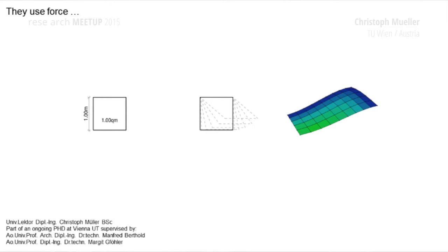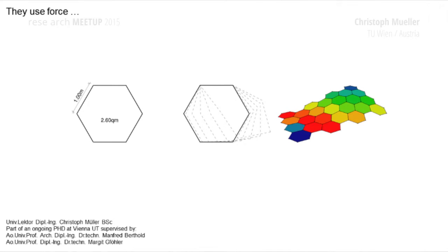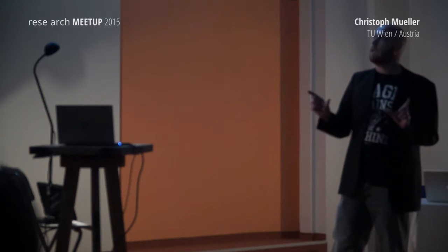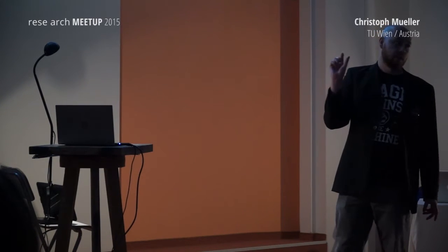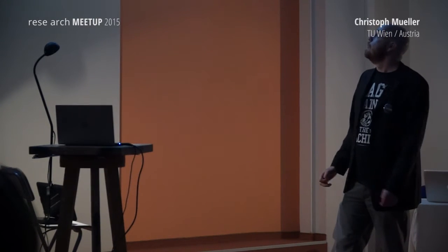The quad is somehow in between, and the n-gon has a lot of efficiency in the areas. So you can create a huge amount of area with the same element size. So the study is always the same element size. As you can see, it's much bigger.